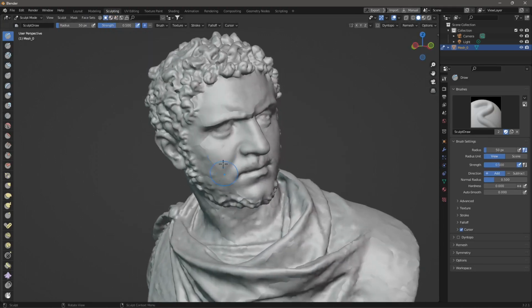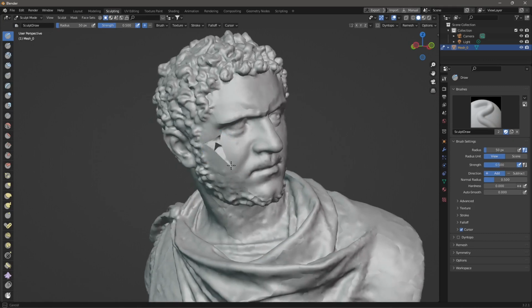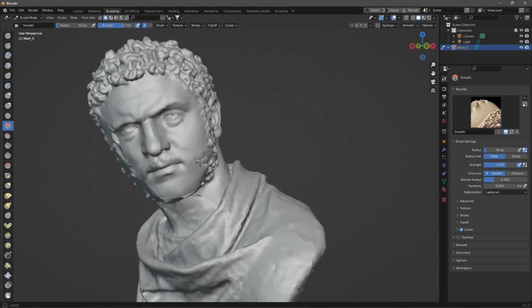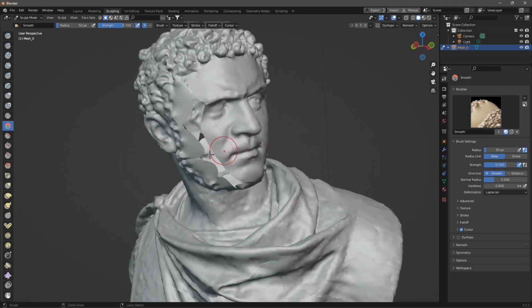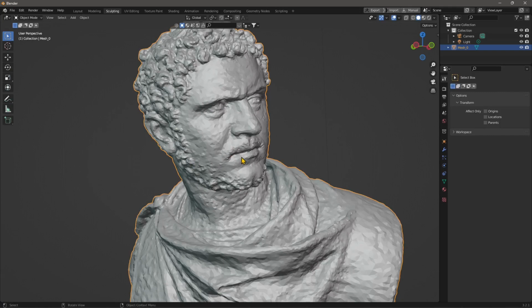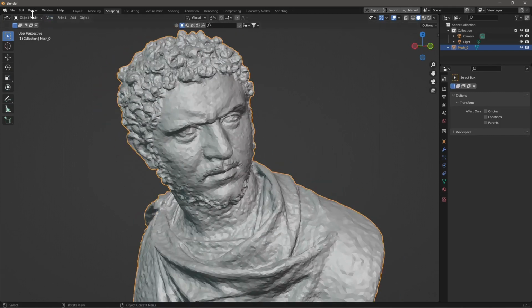Then if I go into the sculpting mode in Blender, I can start to sculpt, and right now I'm using the shift key and the left mouse. So essentially I'm using the smooth brush. You can see I'm smoothing the surfaces, and what happens is that they detach. You can see they're creating gaps. So it's like we have seams, and everything is patched together to create the final 3D solid. But this is not a solid; it's a poly surface.